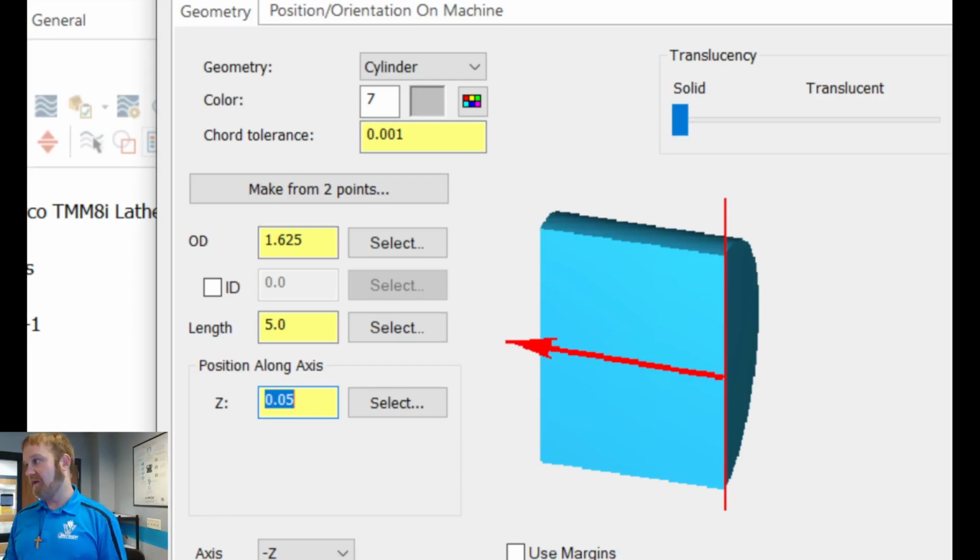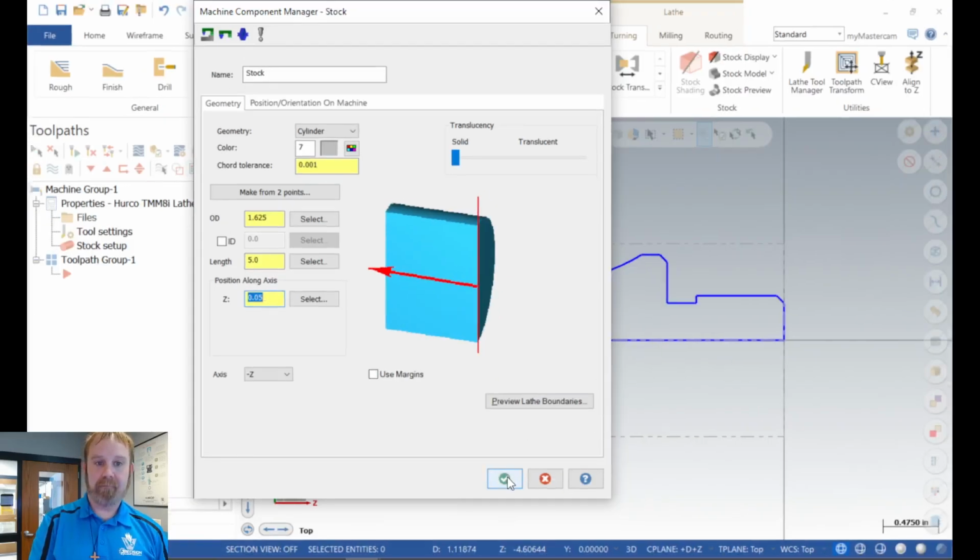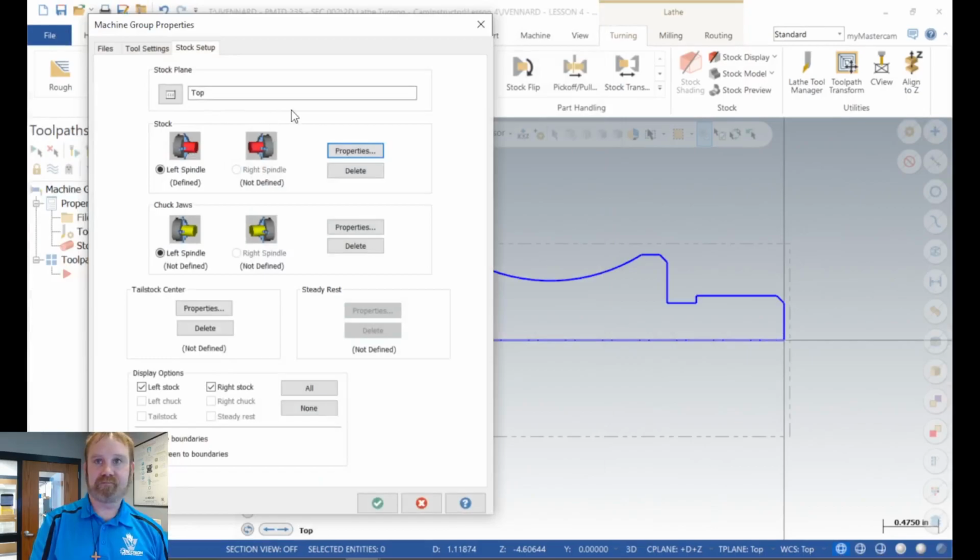I don't want to call it a collet, but it's basically just like a spacer sleeve that makes the spindle fit to the material so it doesn't vibrate real bad. Because if you do have 2 feet of material in there and it goes up to 4,000 RPMs, you might only have 2 inches out here, but that foot that's back in the spindle is still going to get going on you. It'll make the room shake if you're not careful. Okay, we'll hit OK. Chuck jaws.